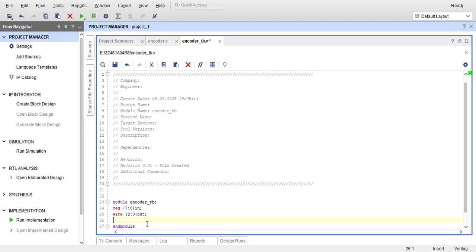Now what are you going to do? Whatever design module there is, it is instanced in the test bench code. By using this line only, these two codes are going to be connected. Whatever design module you have written here, you can make any instance name; you can write your name also. DUT means design under test, a standard name used in Verilog. After DUT you are going to make the port connection. The other two variables you are connecting by order.